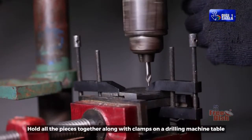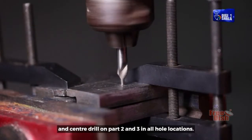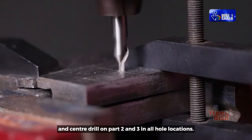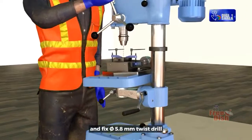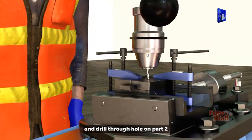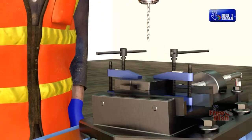Hold all the pieces together along with clamps on a drilling machine table and center drill on part 2 and 3 in all hole locations. Remove the center drill from the drill chuck and fix diameter 5.8 mm twist drill and drill through hole on part 2 to fix dowel pin without disturbing the position of job.